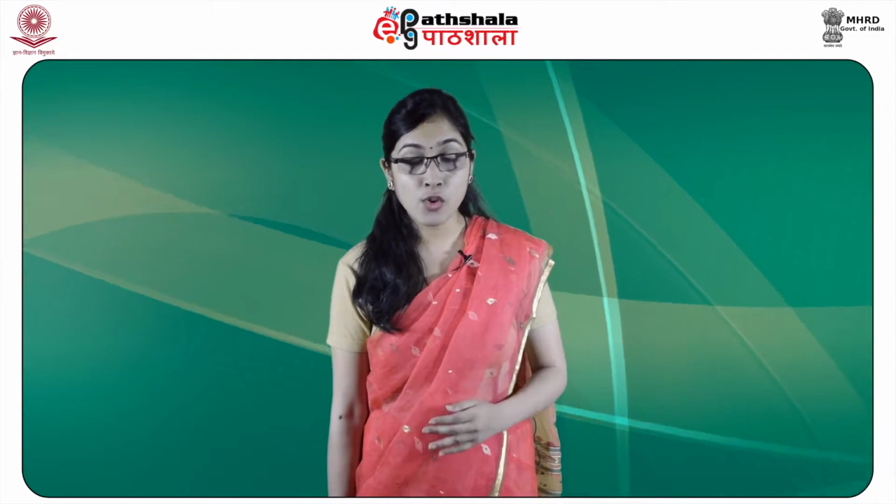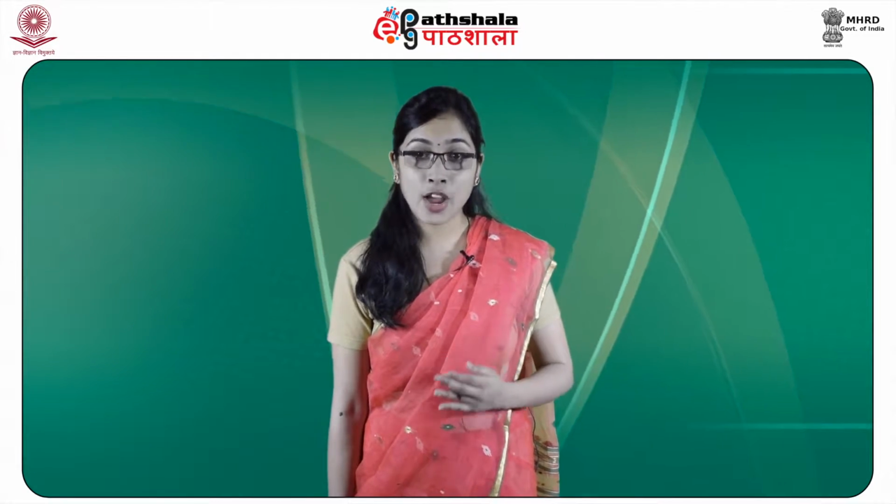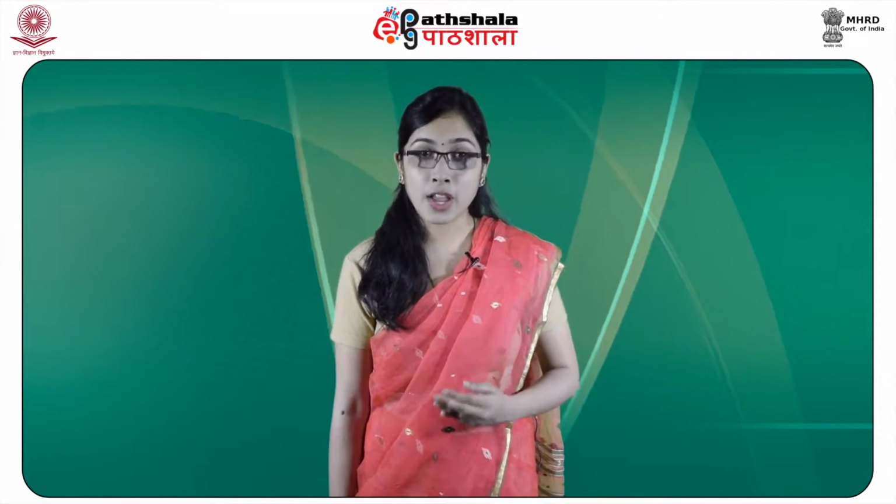Most of the natural fibers such as hemp, bamboo, cotton and wool are spun from short fibers into a sliver and made into roving and then spun or entwined to form a continuous long fiber that may be woven, braided or knitted into a fabric. The resulting fabric usually has a fluffy appearance unless finished, serged or otherwise treated, that results from the short staple fibers from which they were produced.